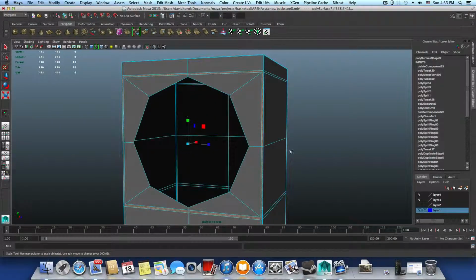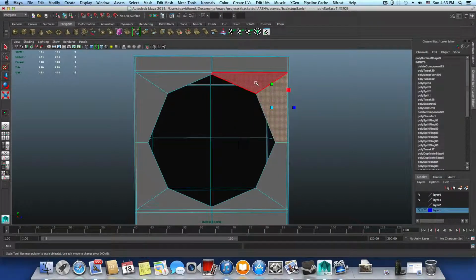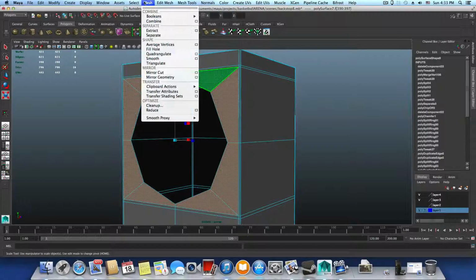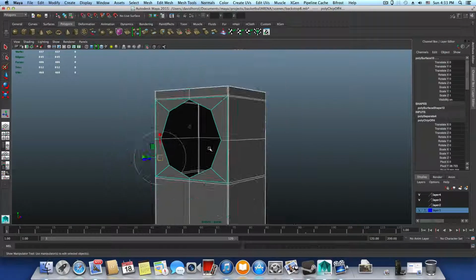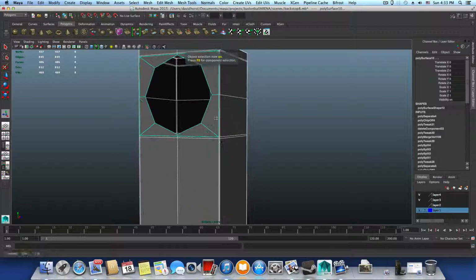Areas, there, I don't know. So what I want to do is only grab whatever is inside this frame, and these are those faces. I want to go over Edit Mesh and Duplicate. So now I duplicate them. I will press F8 three times. 1, 2, 3. Now you can see those in green wireframe, those in white wireframe, just as earlier.